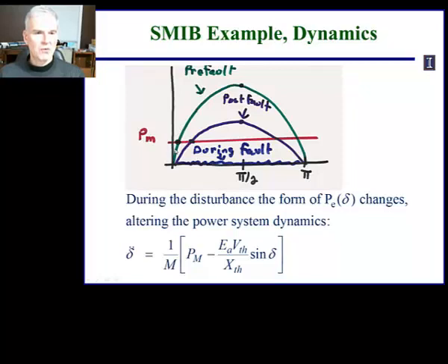Okay, what we had then was an equation for the electrical power out of the generator pre-fault. We had an equation for the electrical power out of the generator during the fault. Since it was a solid fault, in essence, on the terminal of the machine, we weren't able to get any power out during the fault. We cleared the fault by opening one of the transmission lines, so we had our post-fault curve here. Our initial operating point, the equilibrium point, was determined from the pre-fault conditions, and then we're going to see during this slide set that we solved the swing equation here to determine how delta changes with time.